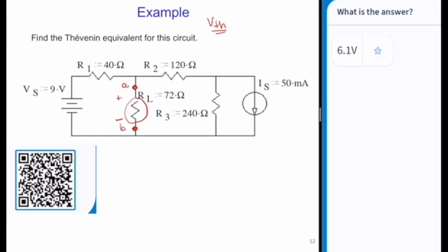Either I can drop that voltage from the 9 volt drop plus the drop across R1, or it's the drop across the R3 and R2. So those are two different pathways. With it open, there's only going to be one current flow, so you can find the current, or find all the voltages across each resistor. And then it should be 9 volts plus the drop in R.